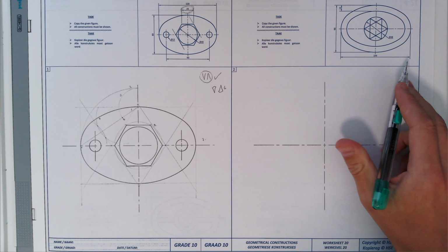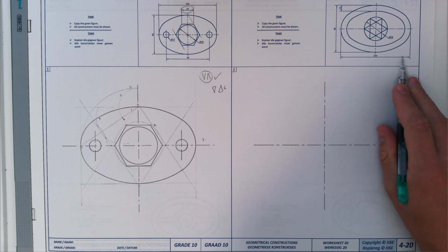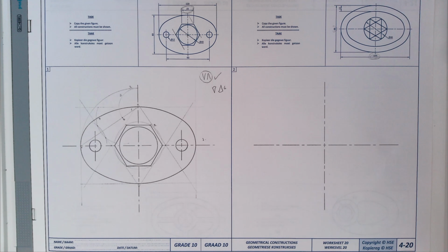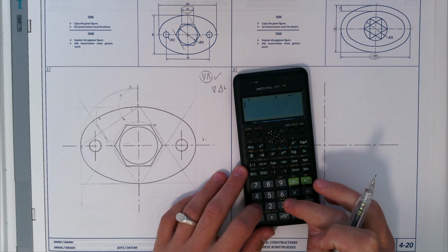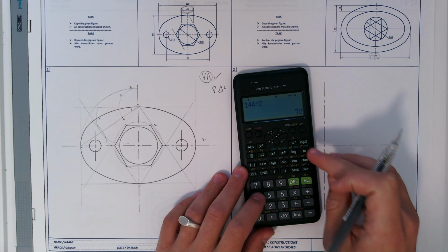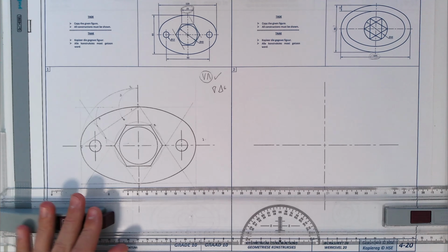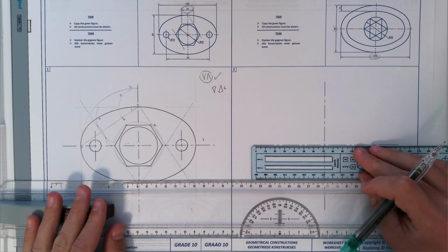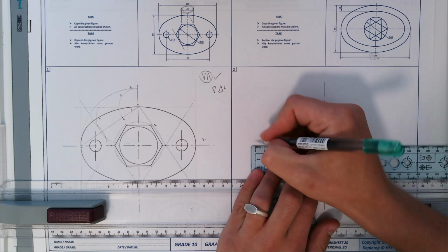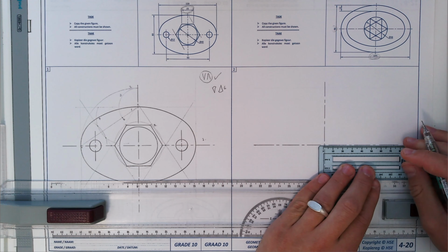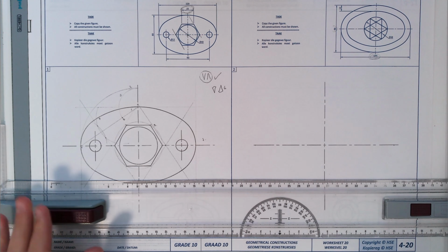If you look at the information here, we can see that it is 144 in length and 96 in height. So we're going to take 144 divided by 2. 144 divided by 2 is going to be 72. So you're going to take your ruler and we are going to make a 72 millimeter dot on the vertical line to the left and 144 in total over there. That should also be 72 on this side. Yep, over there. We're going to make our marks.